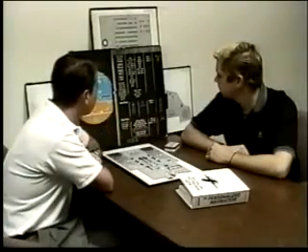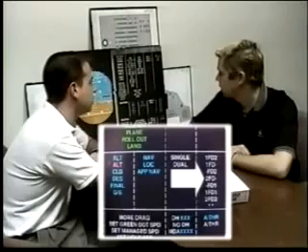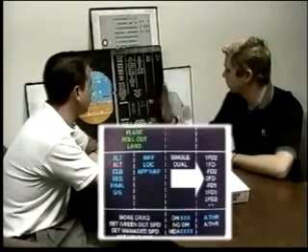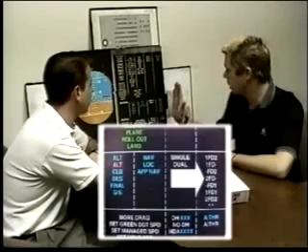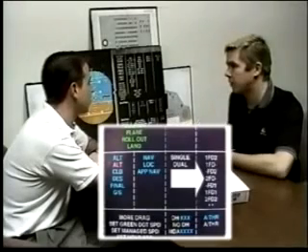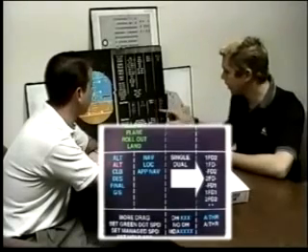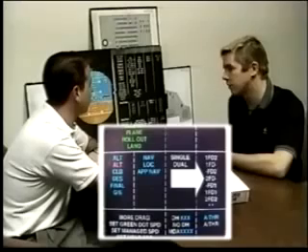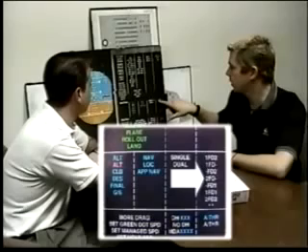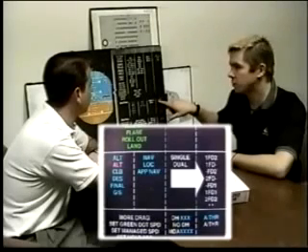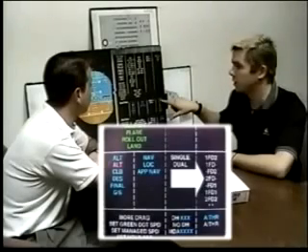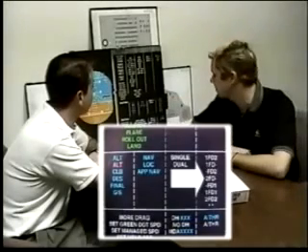Second line, what is that telling you when it says 1 FD2? The first column indicates the captain's situation, the second or right column indicates the first officer's. When a number appears there, that means that flight director has been selected on. The number that's present tells you what system has been commanded. So in this case, the captain's flight director has been selected on, and the number 1 system is providing the information. The 2 on the right side means that the first officer's has been selected on, and the number 2 system is providing the information.